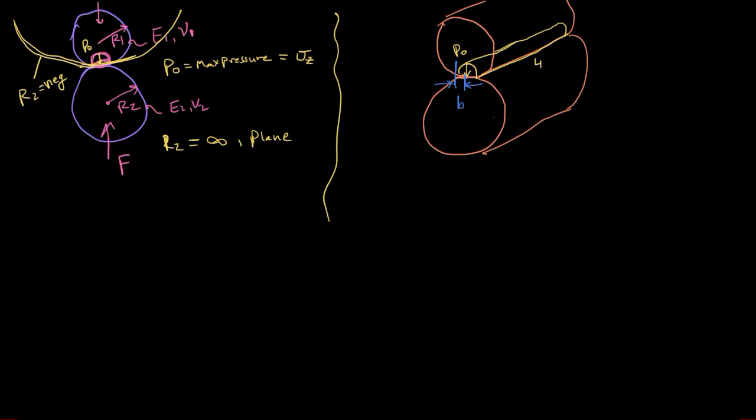And I'll show you in a minute that the distance from that pressure profile to the edge of where it affects, we can actually get some standard expressions for the stresses as a function of that difference. All right, and so in the case of the 2 cylinders, what Hertz effectively contributed was what he called a contact modulus, and in your book it calls it delta.